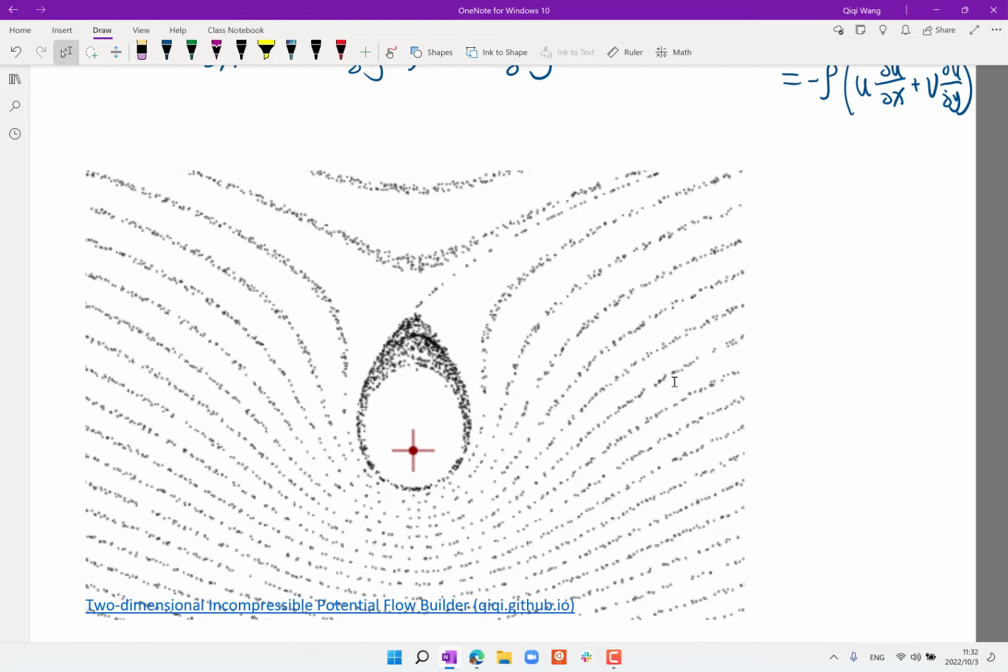By the way, you can think about this as the flow around an airfoil like this at minus 90 degrees angle of attack, if we can somehow magically prevent the flow from separating on the backside of the airfoil. I mean, an airfoil would never stay attached at 90 degrees angle of attack, at least with today's technology. But if we could, the flow field would look exactly like that.